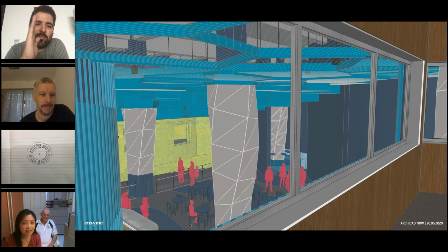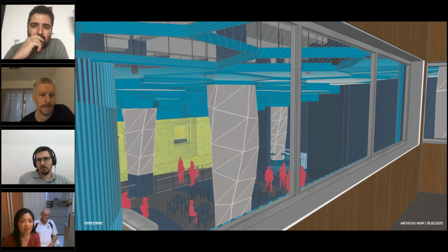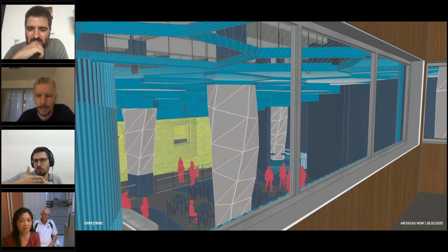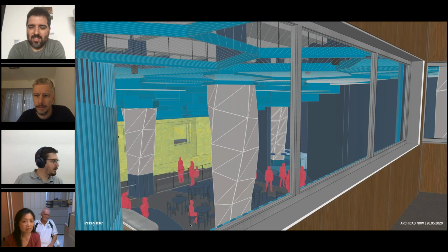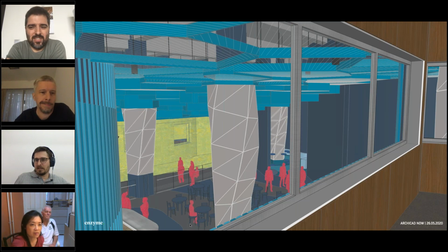Yeah. So basically, those elements will fall in between those gaps, right? Exactly. So we have a hanger detail that will grab those panels from below, and this hanger will be bolted there, and that's why we also need the angles, because we still need to do that on site. How do you call that? Just lay them out on the ground or something. So that allows us to create only one detail that works every time.